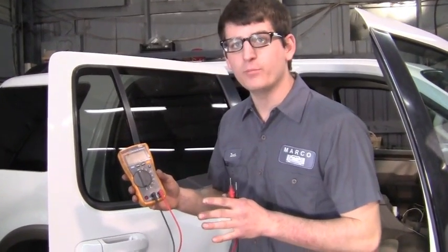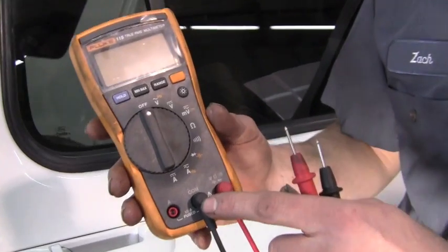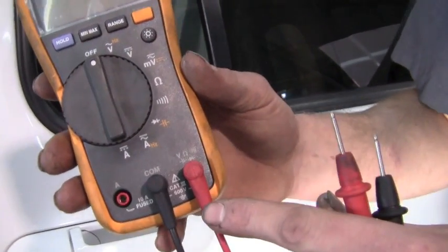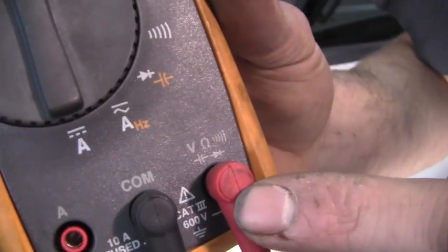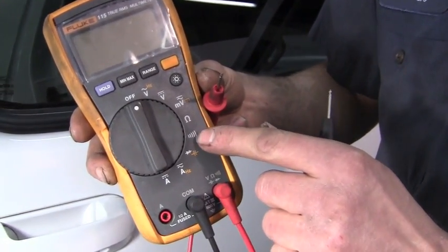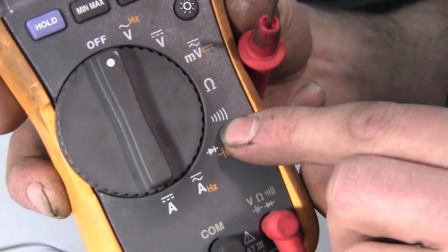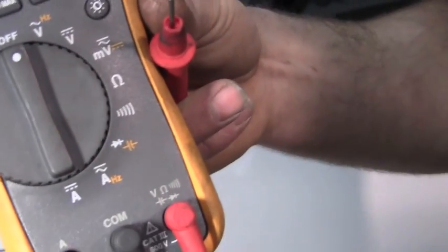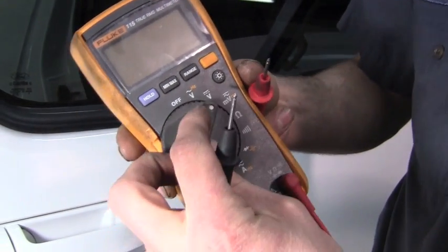When we're setting up our voltmeter for this continuity test, let's make sure that we have one lead in the common hole, and then we have another lead in the volts and continuity and ohm hole. Let's turn our voltmeter on and put it on the right setting. We're going to set it down here on the continuity test, and you can see by the symbol when we place our leads together or close any circuit, it's going to beep, allowing us to know we have good continuity.